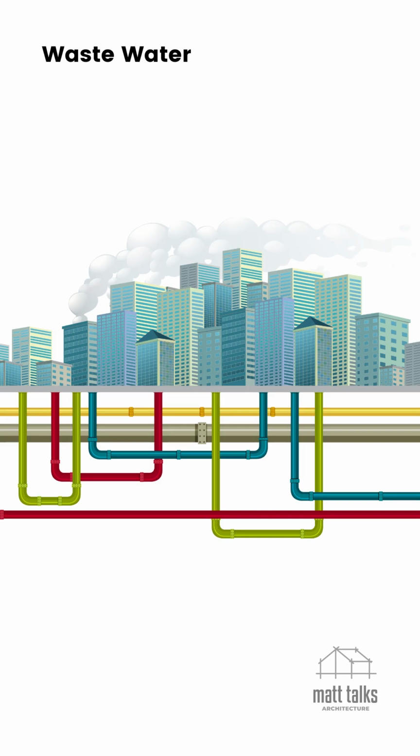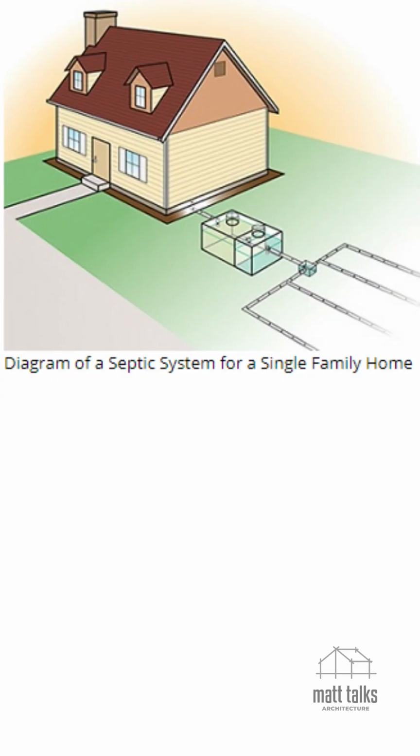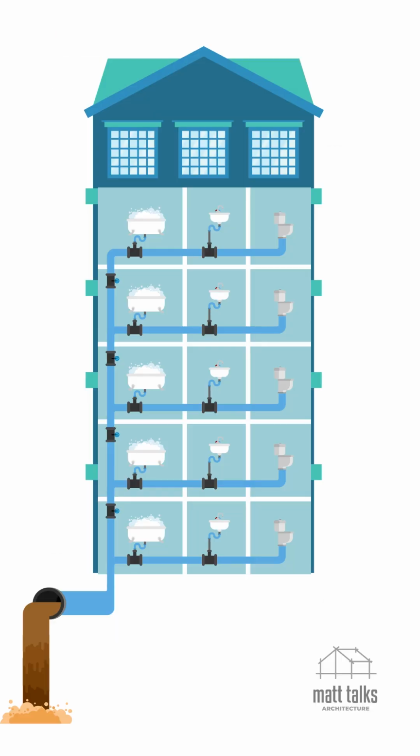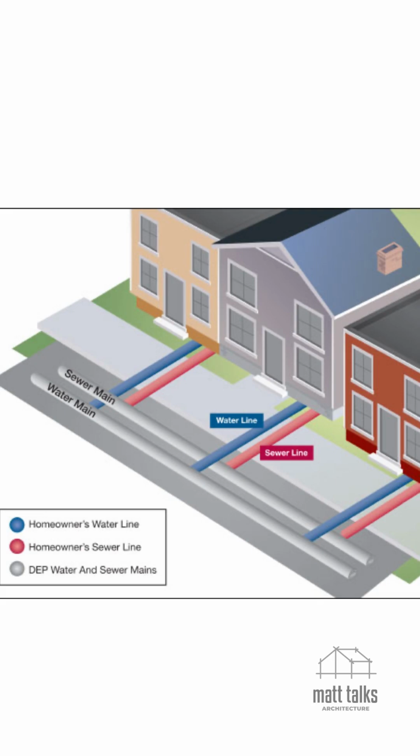Believe it or not, a major facilitator for higher density is having a connection to a sewer line. On larger suburban or rural lots, you generally have more open land to allow for on-site sewage treatment. This includes your typical septic tank, reed bed, and evapotranspiration bed. In urban areas, sewer lines provide a more efficient method than traditional on-site treatment systems. They allow for the treatment of large volumes of wastewater where space is limited.